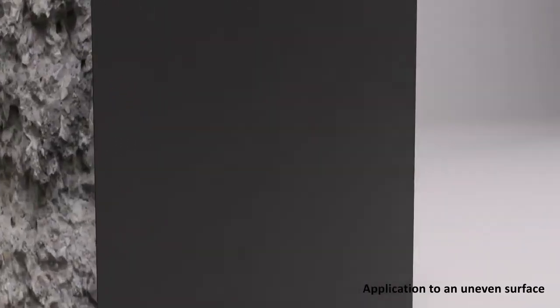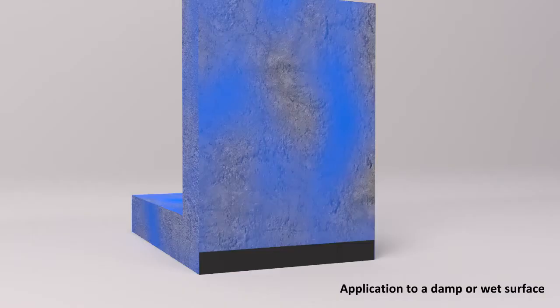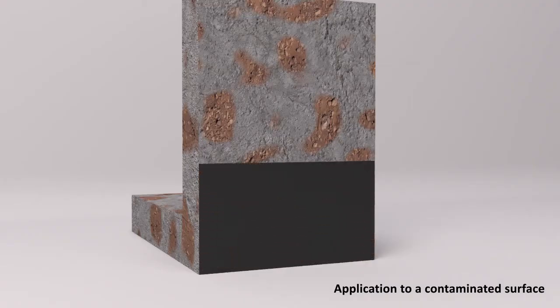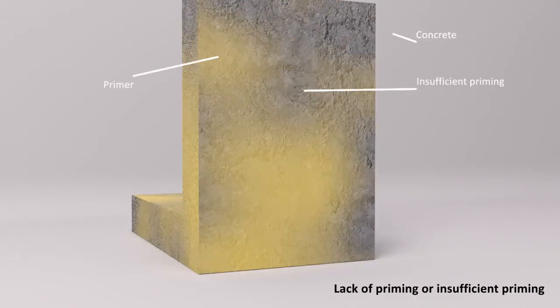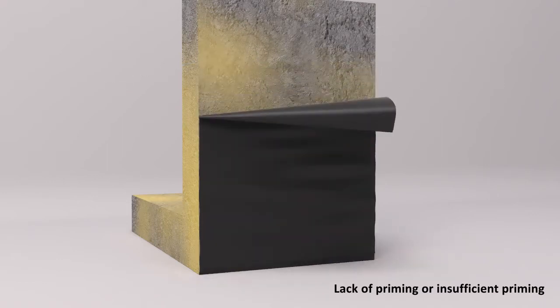Debonding can be caused by a number of factors, including application to an uneven surface, application to a damp or wet surface, application to a contaminated surface. Lack of priming or insufficient priming of the surface prior to installation of the waterproofing membrane can also lead to debonding.